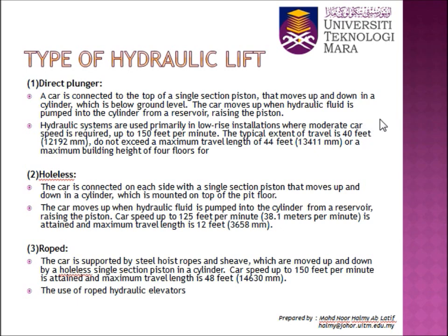Okay, and hydraulic systems are used primarily in low-rise installation where moderate car speed is required up to 150 feet per minute. Okay, the typical extent of travel is 40 feet. Do not exceed a maximum travel length of 44 feet or 13411 mm, or a maximum building height of 4 floors. Okay,